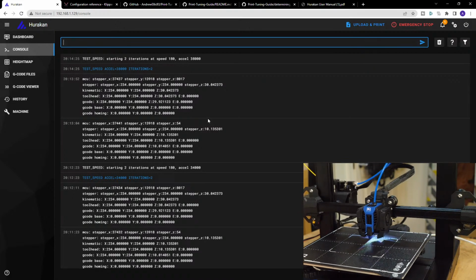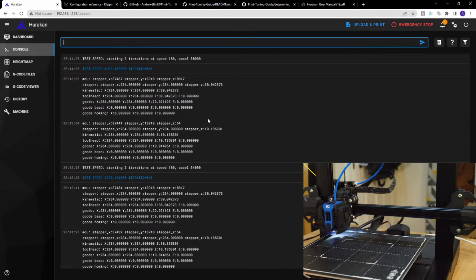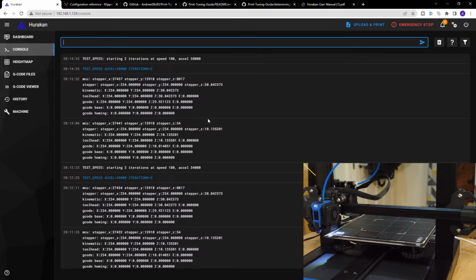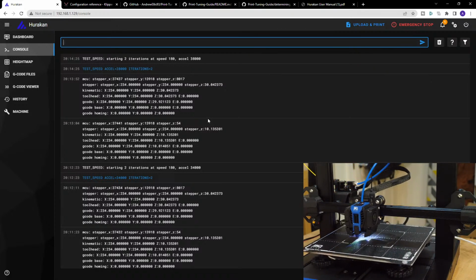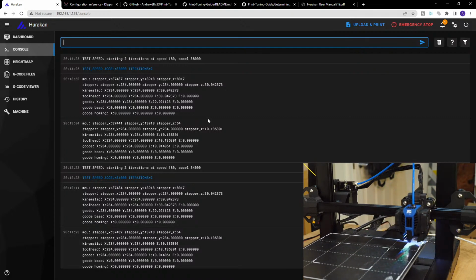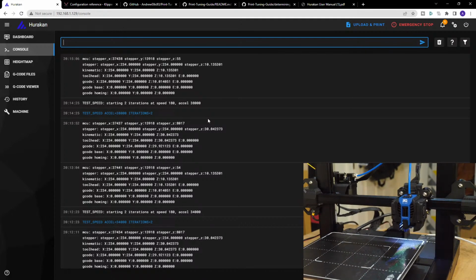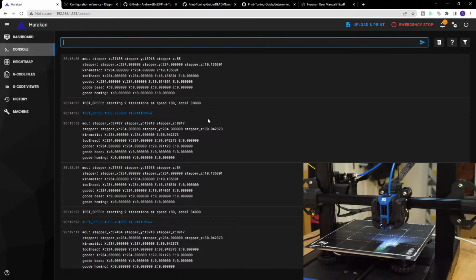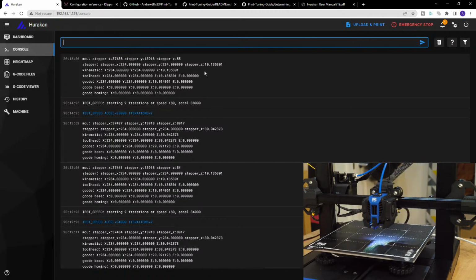So I did a little bit of a test on X and Y with stealthChop. It makes the X really loud. Putting spreadCycle, it makes it really loud. There's some weird noise. Tried a bunch of different configurations to see if it would change, but largely it didn't. But it did change. I've changed it for the Y axis, and that is now on spreadCycle. So hopefully a bit more torque available there, and it stayed reasonably quiet. So now we're just going.